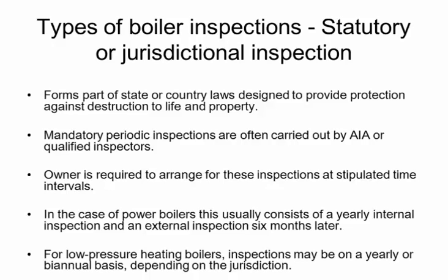Mandatory periodic inspections are often carried out by AIA or qualified inspectors. Owners are required to arrange for these inspections at stipulated time intervals. So there will be a shutdown period where you need to prepare this vessel for inspection by the authorities.